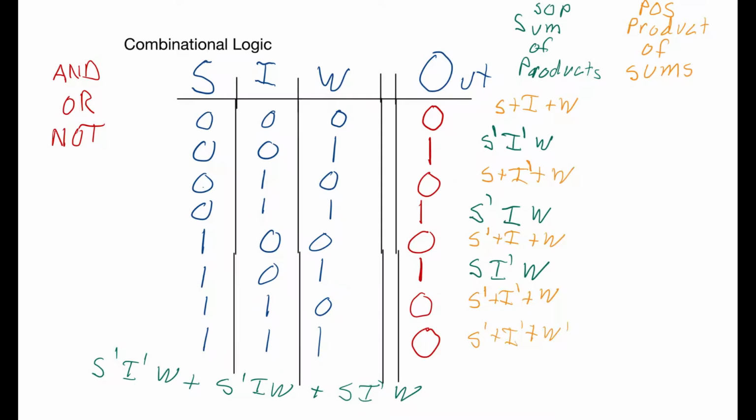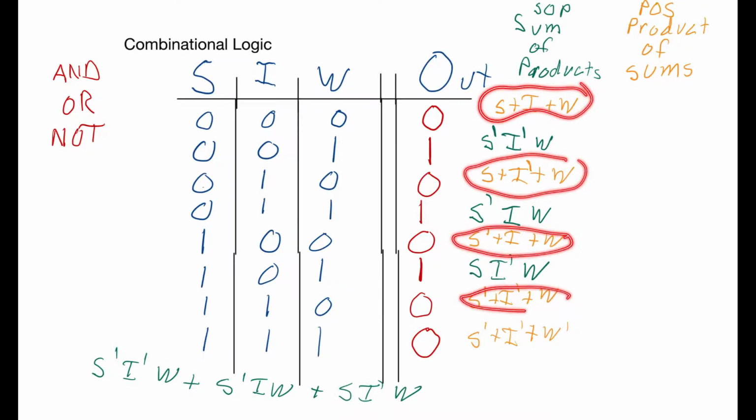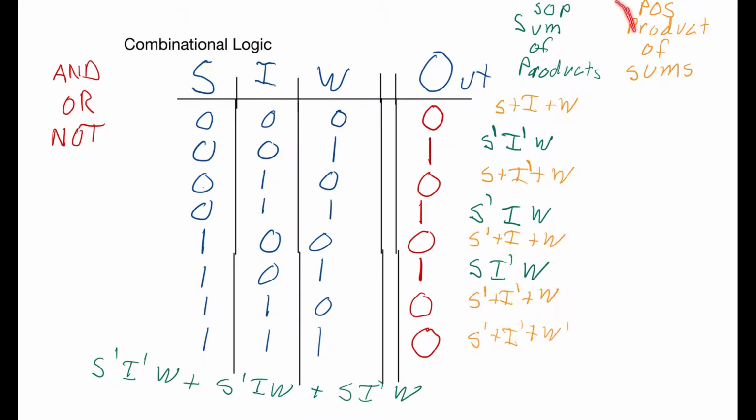All right, so if we look at this line, all three are high voltages, so all three are negated. This line, the first two are high voltages, so they're negated, and this one is not. Then on this line, the only high voltage is the S, and it is negated. So these terms are now our sums, and we just multiply them together.